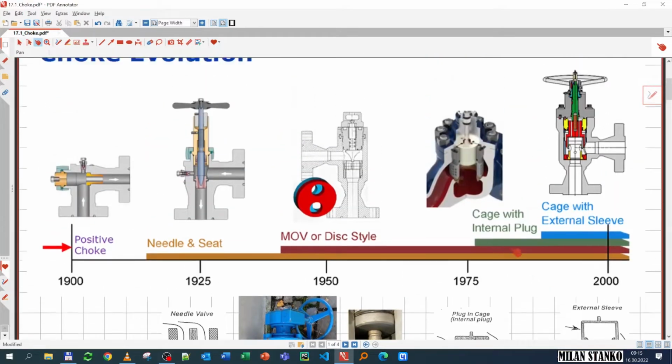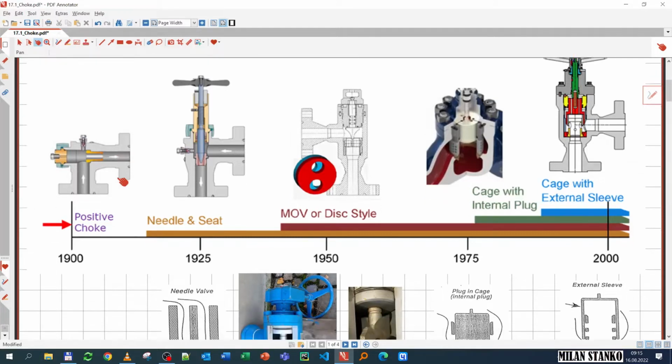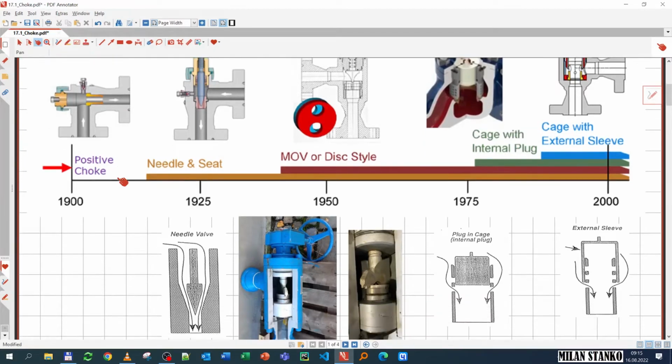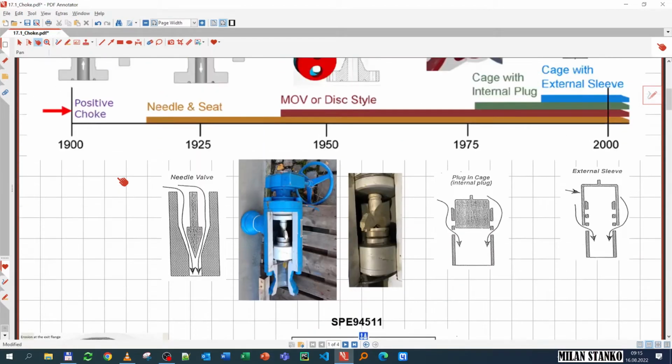Okay, so one problem with chokes is that they are operating in a very aggressive environment. There is a big pressure drop. That means there is a lot of turbulence, recirculation. You also have these high velocity jets that can impact the walls and cause erosion, loss of material over time. And you have flashing, vaporization of gas coming out very quickly out of the oil. So this is a very aggressive environment, and this can negatively affect the life of the choke.